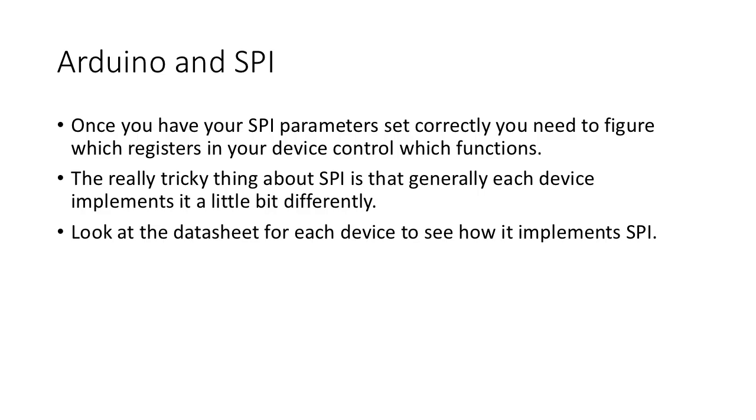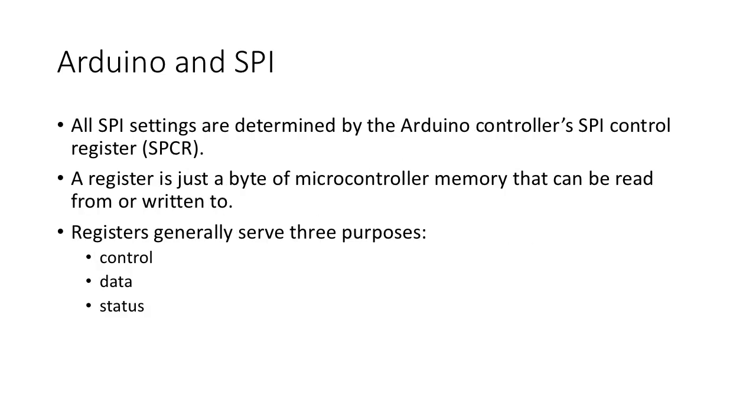You can typically reassign the pins that are used for the master out and the slave in, as well as the serial clock and the chip enable and the chip select. And as a result of that flexibility, you'll find that different microcontrollers, especially those which are integrated with various devices, behave differently. And so you've got to read data sheets, and sometimes you won't find data sheets, in which case you have to sit there and test which pin goes to which pin on the chip. And you may do that with a continuity tester or with simple inspection and tracing of the board traces.